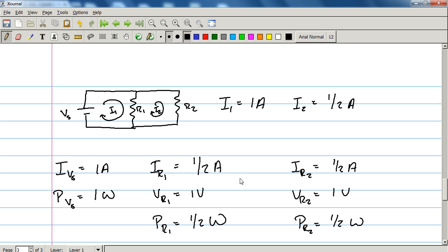So remember, negative just means you need to flip the sign around. It just means the direction you picked is the opposite of the direction things are actually moving. So if I'd picked I2 minus I1, it means that the current is actually moving up R1, as opposed to I1 minus I2, where current is moving down R1. Because I1 would be greater, it would overpower I2, and this direction would follow. If I2 is bigger than I1, this direction would follow through and it would push up.